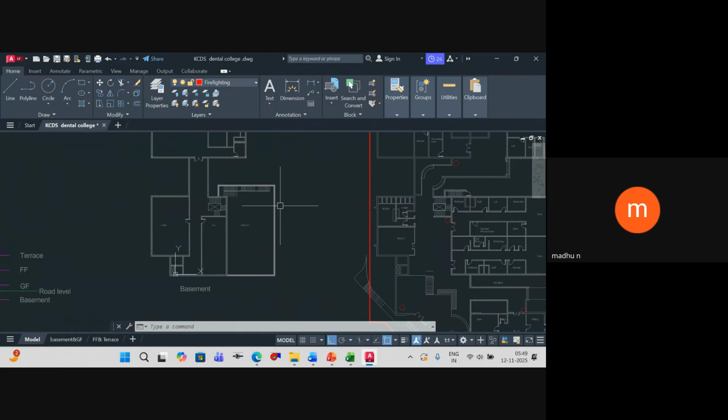Yeah. If you want to enter your pump room, don't enter through the building. Try to provide it from external to the building so that it's easy in case of crisis, which makes sense, right? Because if there's a fire, obviously, if someone wants to enter the pump room, it might or might not be possible. That's the reason, number one. Or if it is not possible due to architectural constraints, then from external to the pump room you should have a separate fire exit path with at least 2 hours of fire rated medium.